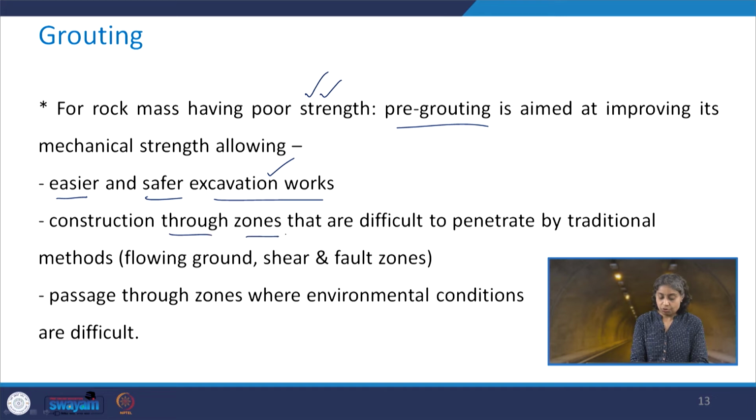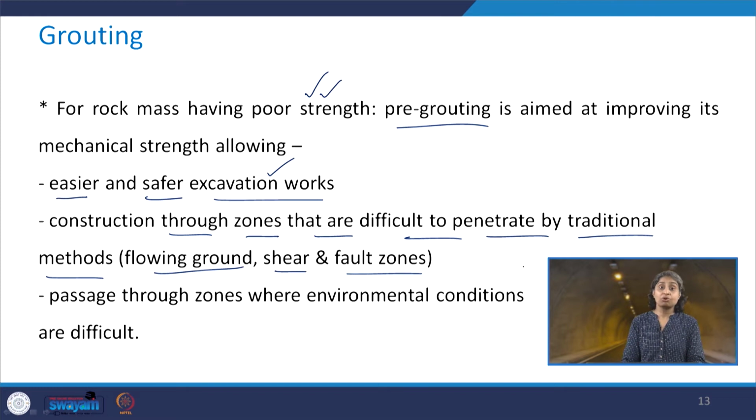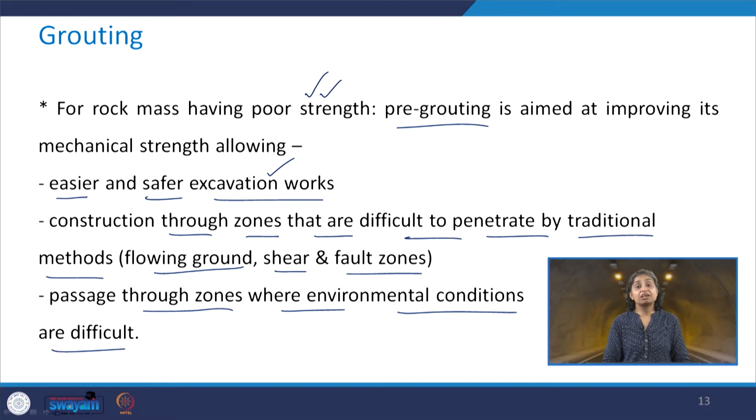It also helps in construction through zones that are difficult to penetrate by traditional methods, such as flowing ground, shear and fault zones. Then for passage through zones where the environmental conditions are difficult, pre-grouting helps in the excavation work.